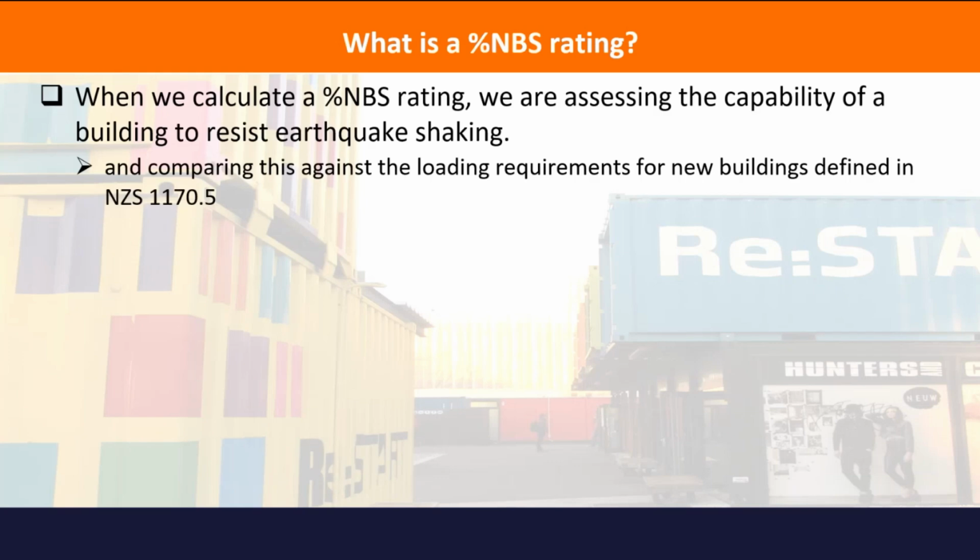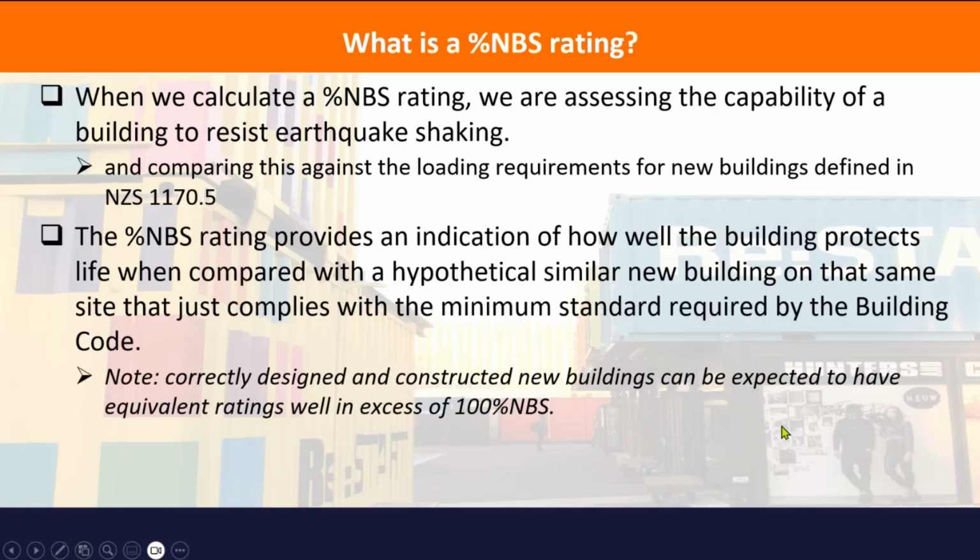So what does it mean? Well, we're assessing the capability of a building to resist an earthquake, but it's not the full whack that we put on a new building. And we compare it against the loading requirements of our standard, a new building standard 1170, part 5. So it's just an indication of how it's going to perform against a similar earthquake.